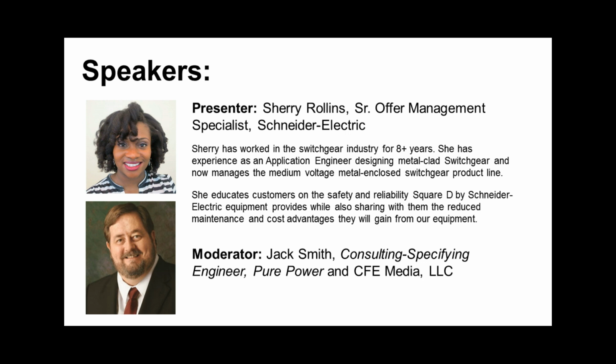So it's a very manual means, and it's a device you insert in lieu of a circuit breaker. The second method typically used in withdrawable switchgear is a very manual process where one puts on their PPE, uses a hot stick and a cable grounding assembly, and physically connects cable between the bus bars and the ground bus. Obviously, there's some exposure or potential risk with that activity if there is still accidentally energized potential. So those are the practices on withdrawable switchgear. That's very common.